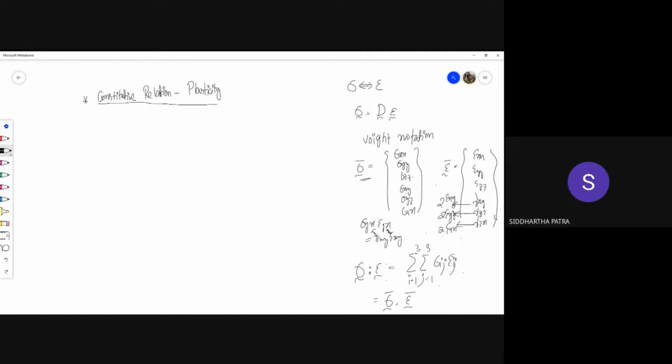So when it comes to the strain components, the shear strain components, a coefficient of 2 is put in the so-called engineering notation. Now this is different from engineering strain. Okay, so that engineering and true strain, that is different. Okay, here it is engineering notation or Voigt notation.